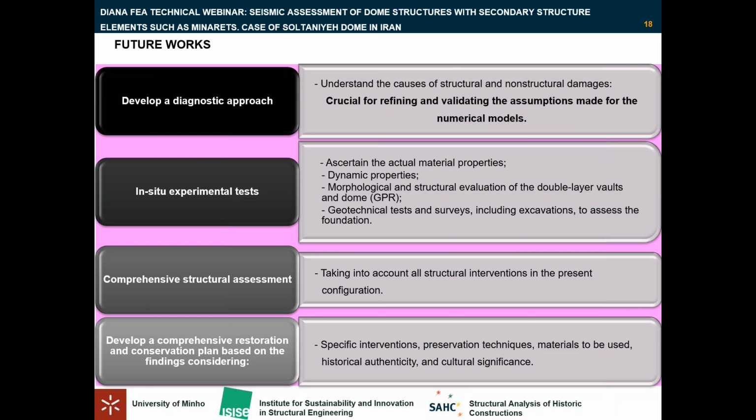diagnostic approach to understand the cause of structural and non-structural damages, which is crucial for refining and validating the assumptions made for the numerical models. Also, the performance of in situ experimental tests to ascertain the actual material properties, dynamic properties, morphological and structural evaluation of the double layer walls and the dome, for example, by using GPR technique, geotechnical tests and surveys, including excavations